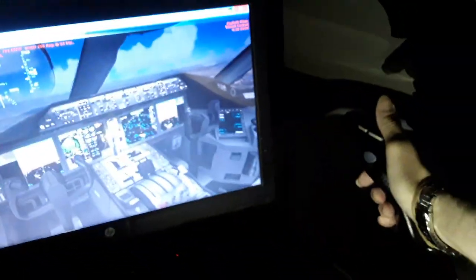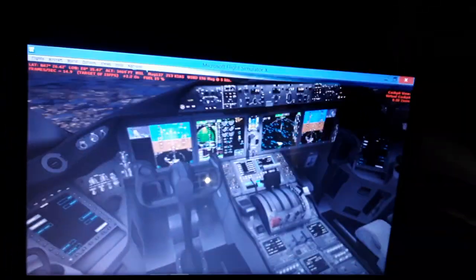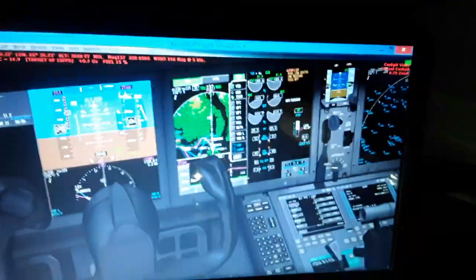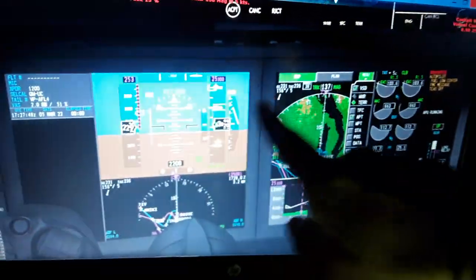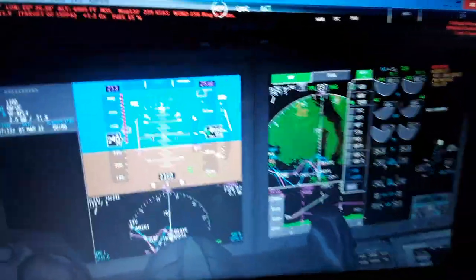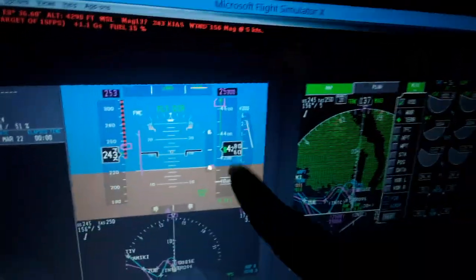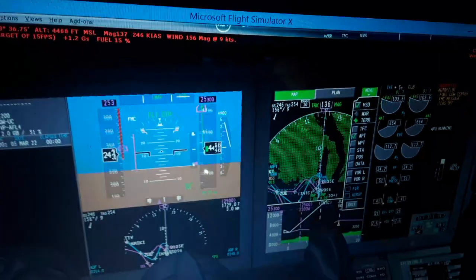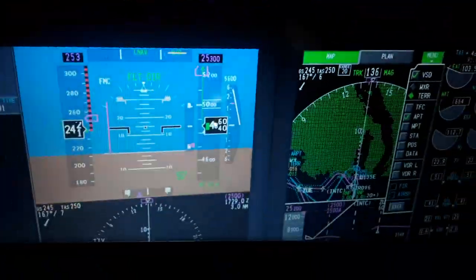So we have the takeoff over here, as you can see. So we keep climbing. You can see all the instruments of the Boeing airplane are correct after takeoff. You can see here we have the terrain, red, green, yellow. You can see the airspeed 230 knots. The altitude, we are 2,400 above the ground, but 4,200 above the sea. We climb with 5,000 feet per minute right now.